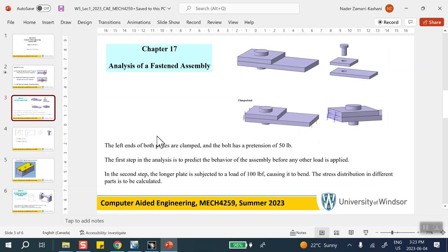Now, it is important to realize that my request from you is never to cut through the bolt. So you have to use as many planes of symmetry that you have here. Obviously, here there is a plane of symmetry which is right along the longitudinal direction, but that cuts through the bolts. So do not cut through the bolts, as you were asked repeatedly in the past. Never cut along the length of the beam, in the axial direction.